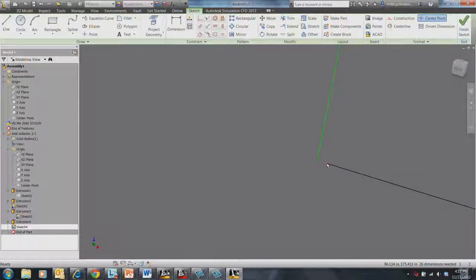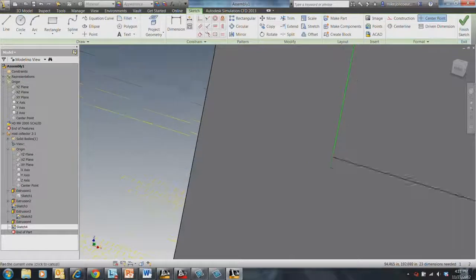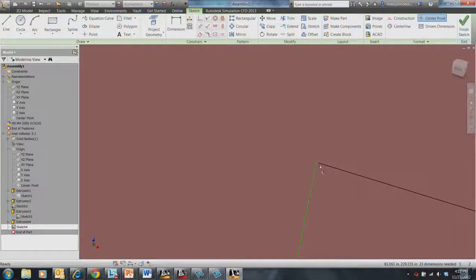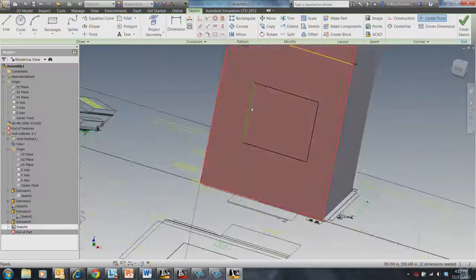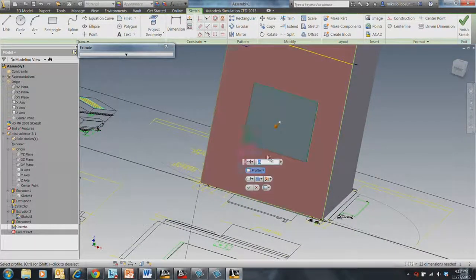The nice thing about it, this one I can actually see it. So by using Inventor, I can very easily take and control these or close them up. So we'll take a look here. Yep, I got another one right there. Just go drop that in. Oop. We'll get that again. Right there. Okay, so now, going to extrude that. We'll bring that out 12 inches.